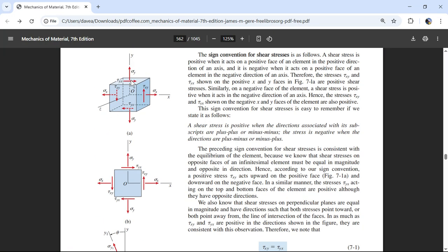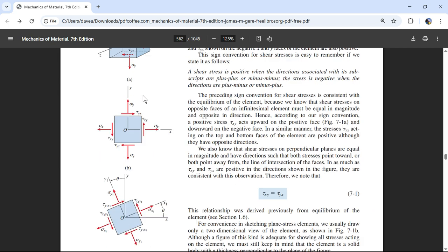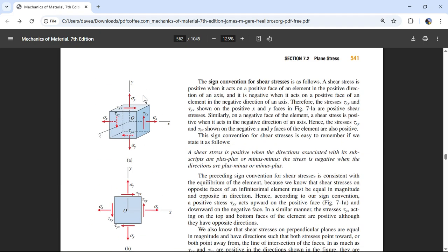If I do take this cube, these are the pressures, but these pressures act on surface areas, and these pressures are related to forces. So even right here, they should have drawn another diagram, a free body diagram of a 3D cube, where right here, instead of a tau, which is a pressure, I should have an arrow that's a shear force with the letter V. Because I think us as humans, we can understand forces better than pressures.